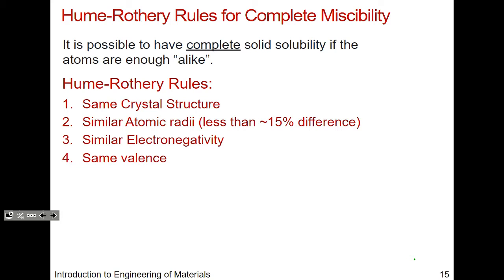Now, you probably have heard of steel, where there's iron and carbon. Carbon is much smaller than iron in terms of atomic radius. So you can incorporate carbon into interstitials. So in between the crystallographic sites that we have talked about, right? So for FCC, there are atoms at the corner and atoms at the faces. But there are gaps in between those atoms that we talked about. Carbon can go right there.